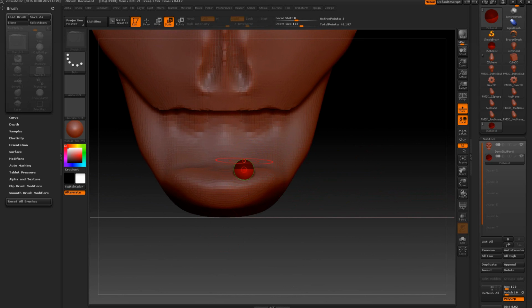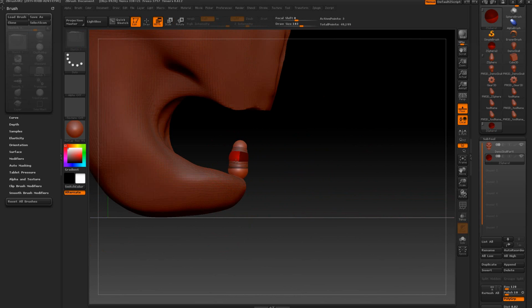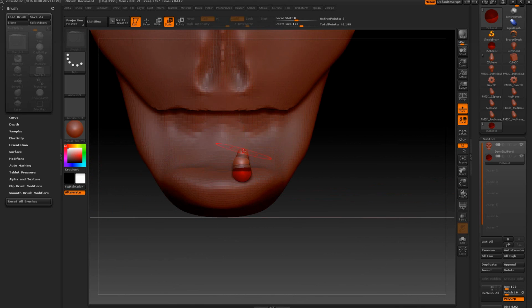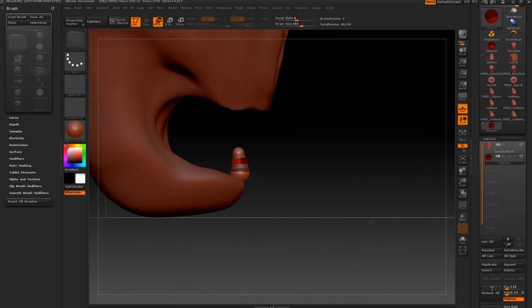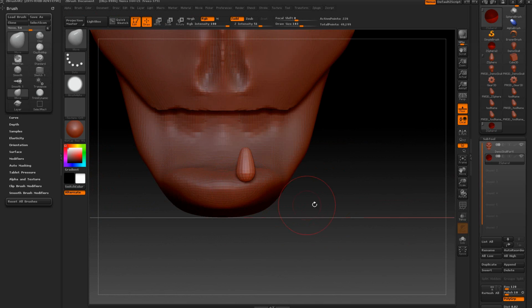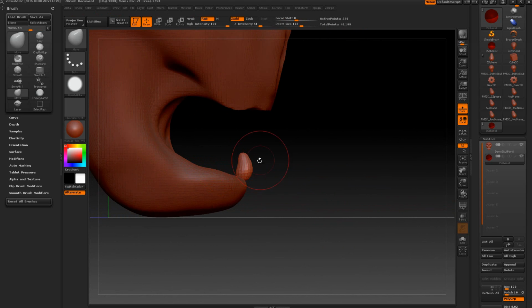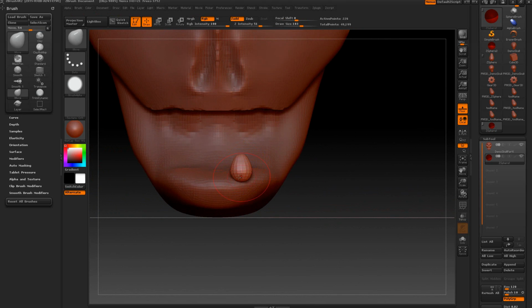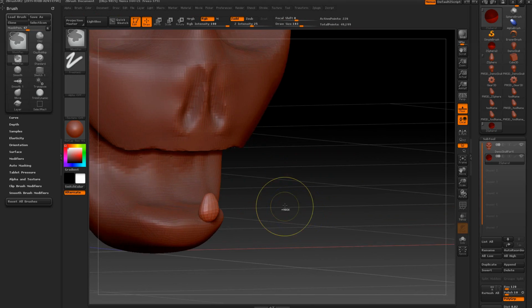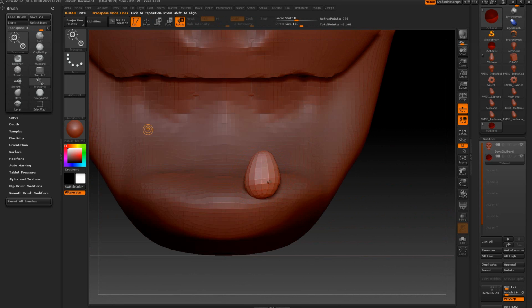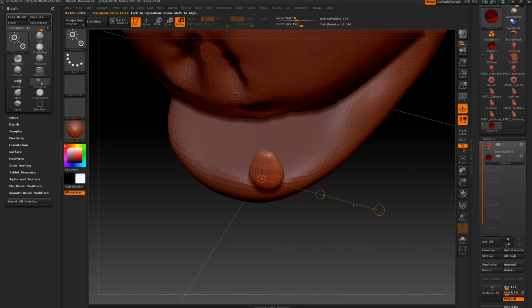Scale it down and draw another Z-sphere on top by pressing Q, clicking on the surface of the Z-sphere. Rescale them if needed. And then when you're ready, press A and have your tooth ready. You can then change its shape using the move tool and flatten it out like this. You can press R and rotate it the way you want it to be in the mouth.